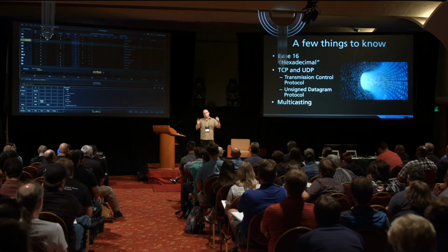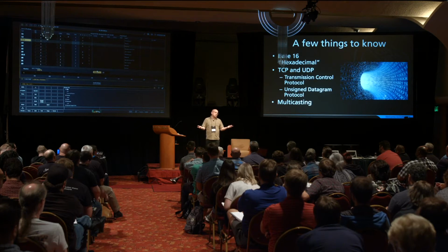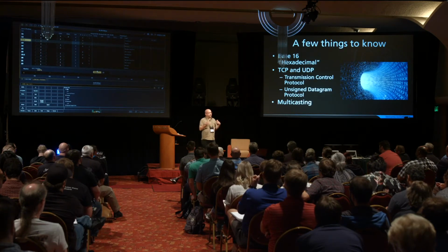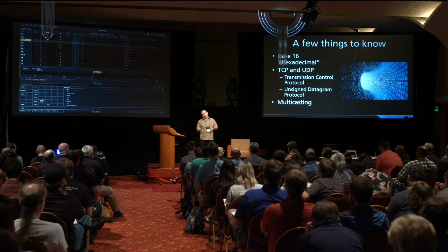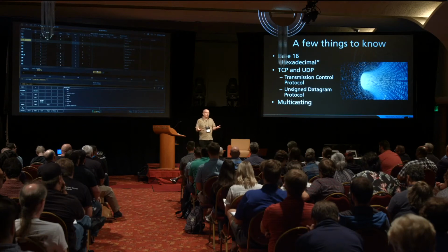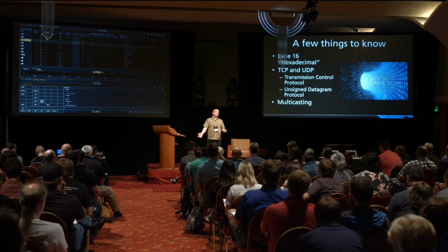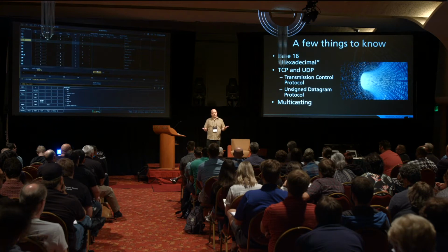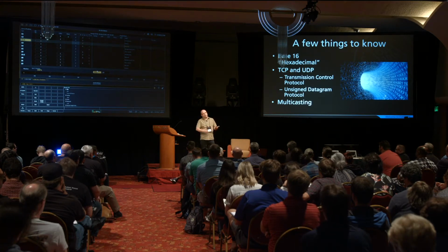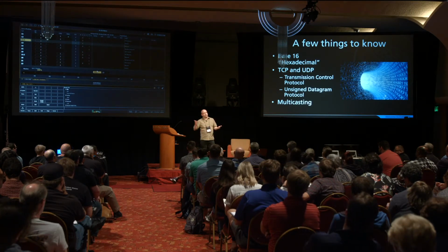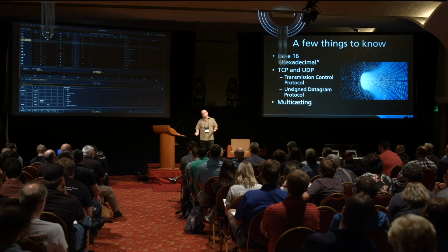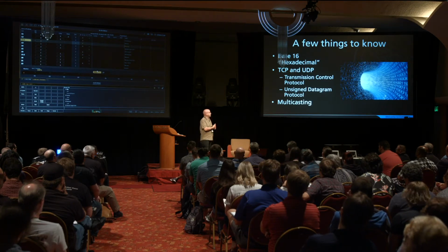We send the message out. It might get there, it might not get there. The nice thing about these streaming protocols is if it doesn't get there, there'll be another one in a minute. DMX actually works the same way. There's no reply in DMX. There's no guarantee that it got there because we're just going to send those 512 channels over and over again. So if one chunk gets lost, it doesn't really matter. There'll be another one in a minute.